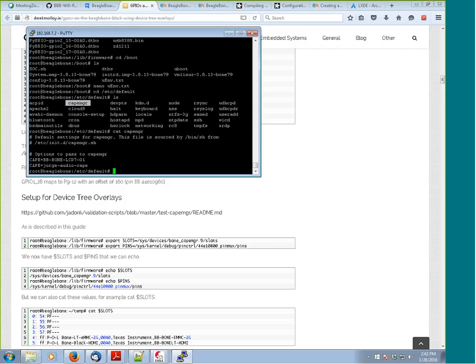And basically what I ended up having to do is, in the case of the LCD screen, apparently part of its work, it actually automatically added to this file. It had cape equals the LCD, so that way from default it would always start up. And then I went and I added my audio cape. And that basically makes sure that whenever the radio turns on, both capes get loaded. Even if it fails once, it'll keep trying until the cape gets loaded.